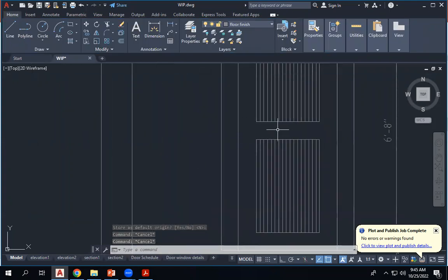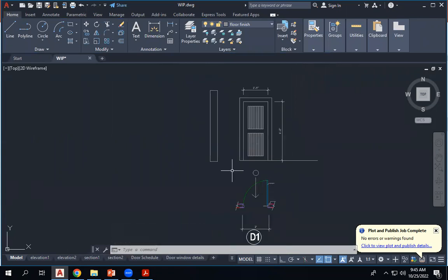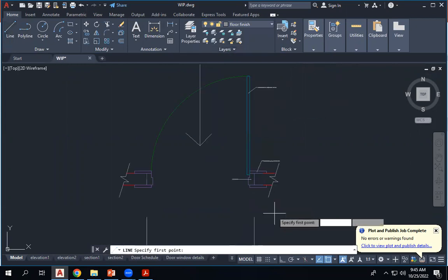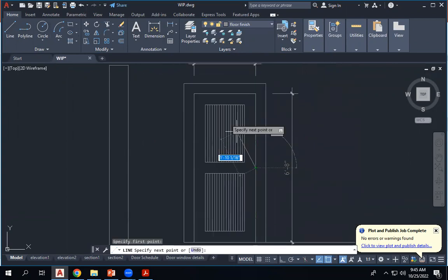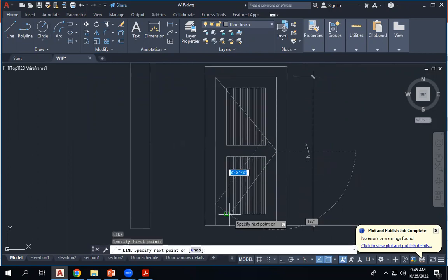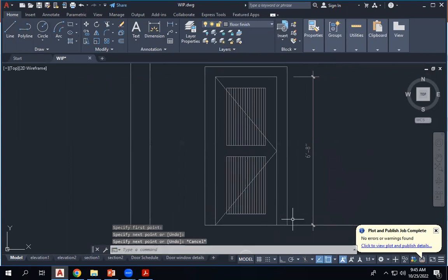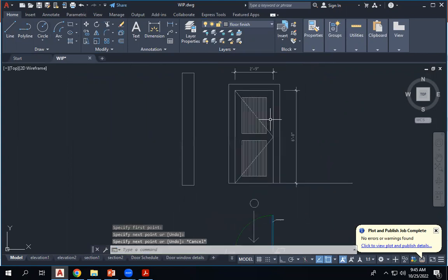And you can draw the handle here. And for this one, the direction of the door should show where the hinges are. So what you draw is like this. Where the hinges are, the line is like this. So the door is opening.